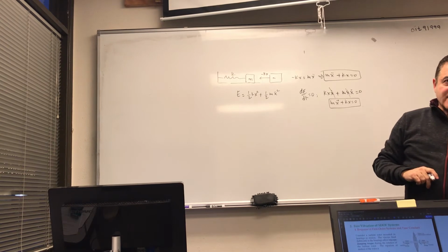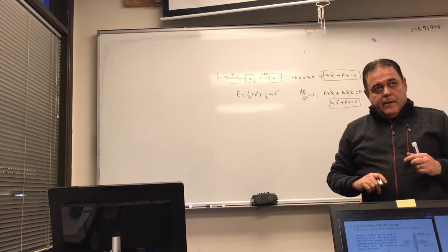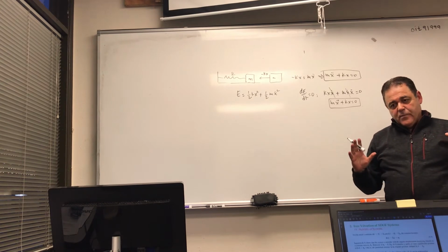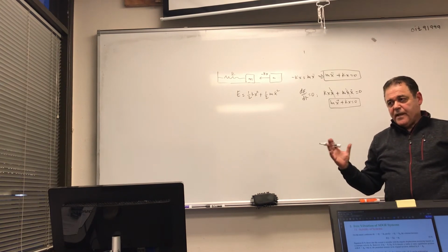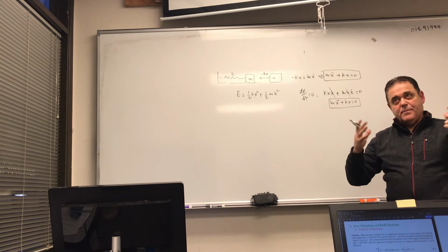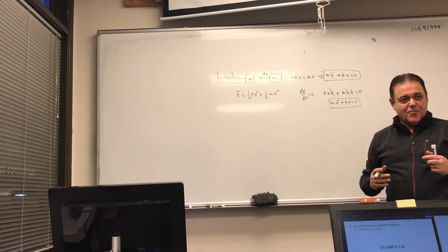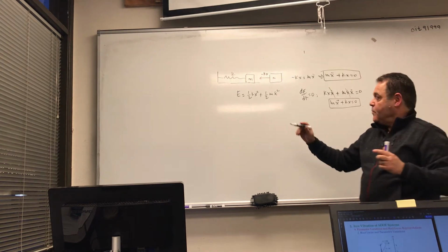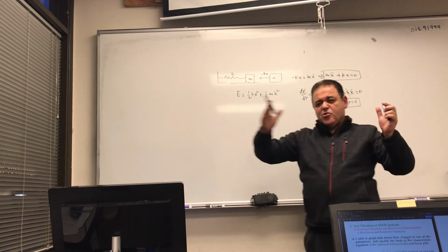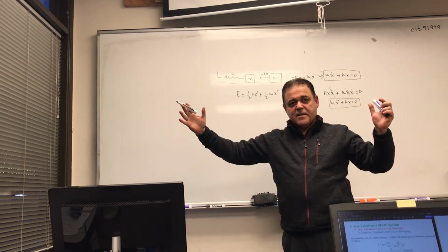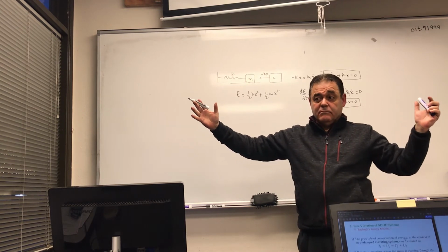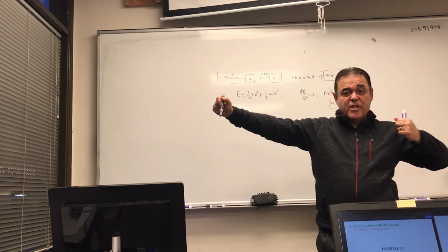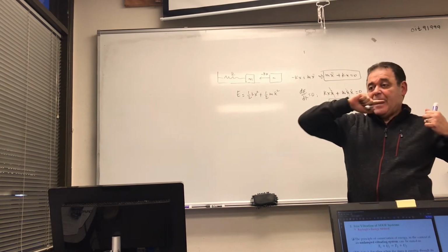Now Rayleigh comes in and says, let me give you a third method. In a vibrating system, as we talked about before, the energy is being tossed between the mass and the spring. When the mass is at its extreme position, its kinetic energy is 0, and the spring is the most stretched, so the potential energy of the spring is highest.